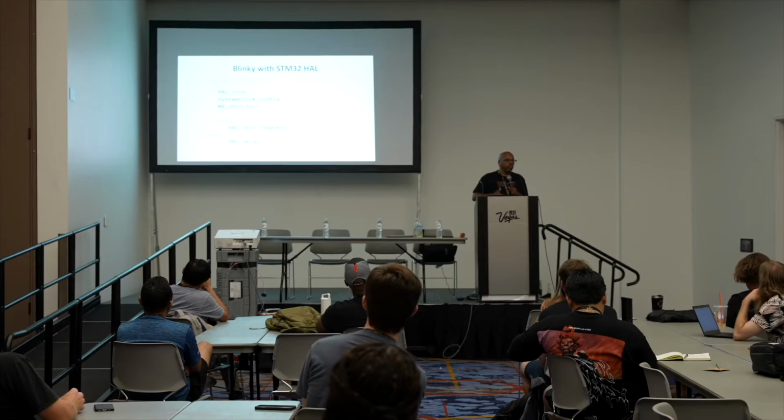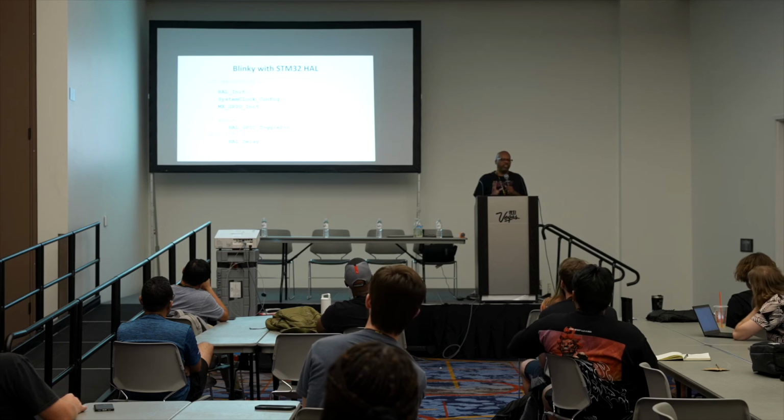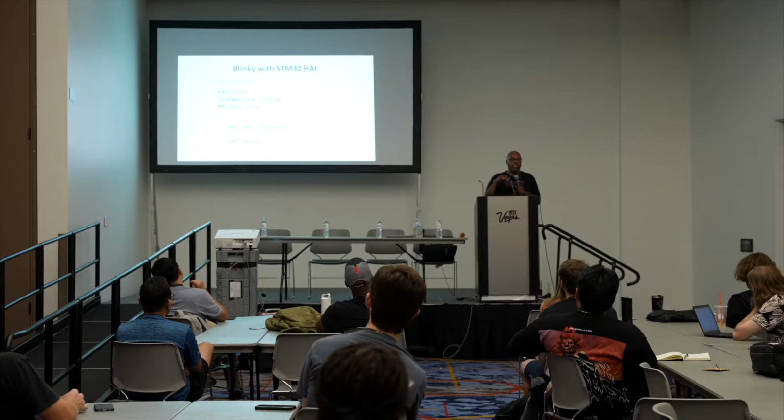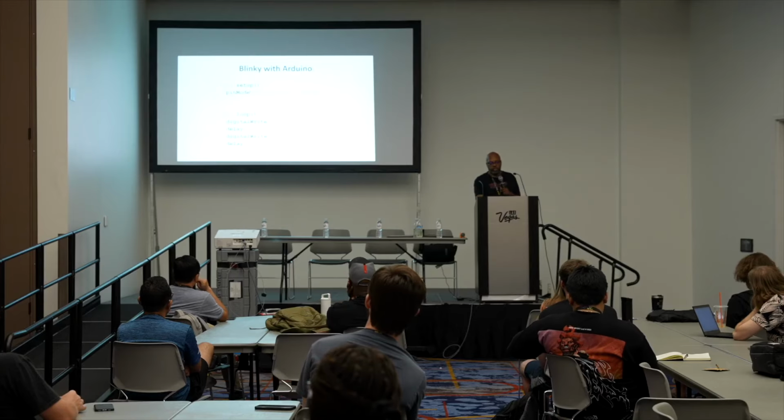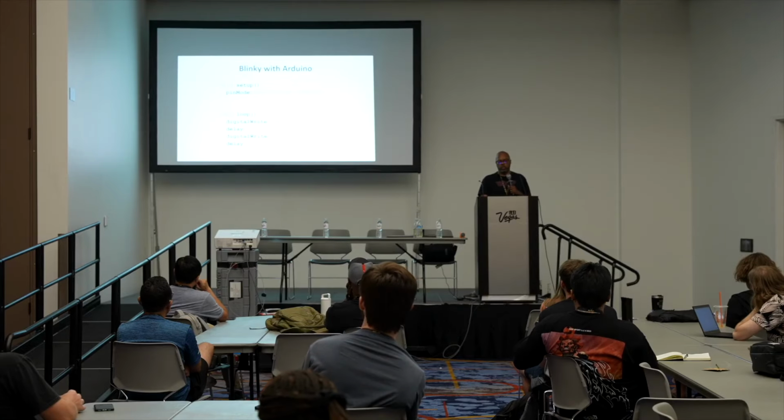But you initialize all these peripherals, and you don't need it. This one is for GPIO init, but you have to do the HAL init too. I don't quite understand the relationship there. But when I look at the code of them, it's a lot more stuff than I did. So anyway, that's HAL. And then with Arduino, here's how you might write it: a setup and a loop, and digital write is their function.